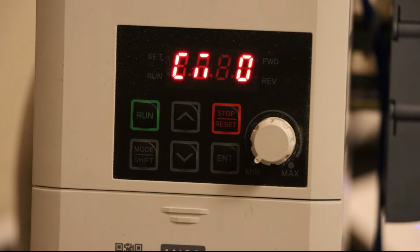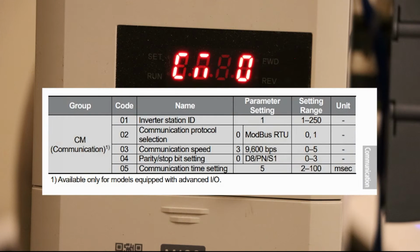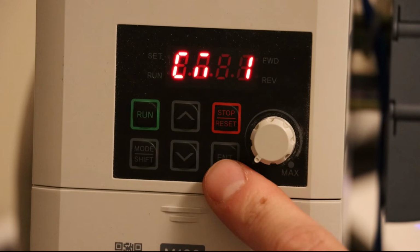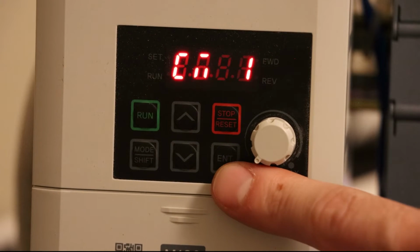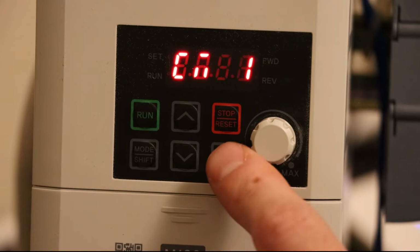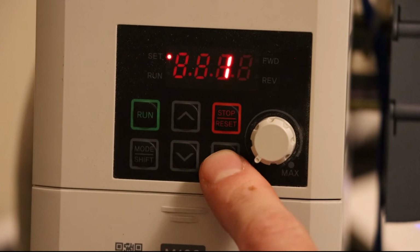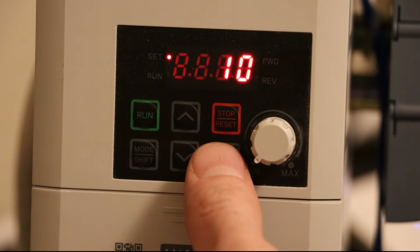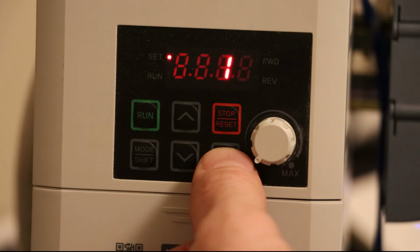So the way this CM works is there's a bunch of codes for the CM. We're on 0 at the moment, which is nothing. As we go up through the codes, we can change different criteria about our communication settings. So if we go to CM1, that should be, according to the datasheet, the actual inverter address. So this is our Modbus address. So if I go in here, you can see I've already set this to 10. So this VFD is sat at address 10.